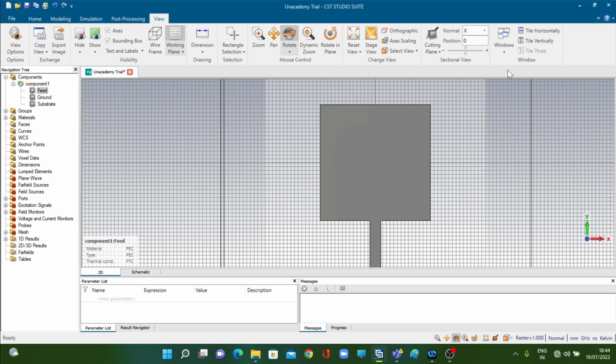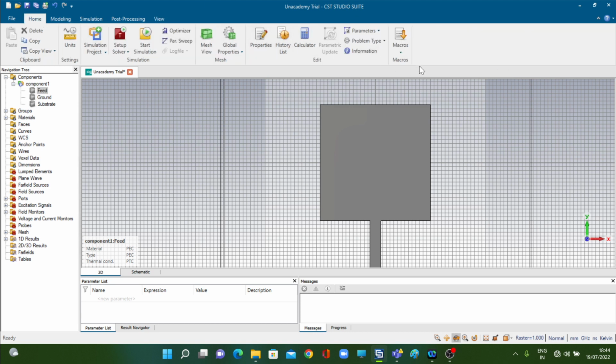And we will start off with the modifications. Now, like I mentioned, we will cut slots at the beginning. I hope all of you remember what the Boolean addition operation was. The Boolean addition operation is basically combining, joining two different structural components. Generally, those two structural components are of the same nature, either both are metals or both are dielectrics. Very rarely we join a dielectric with a metal, or more generally two different materials, because that will not have a profound effect on the simulation results.